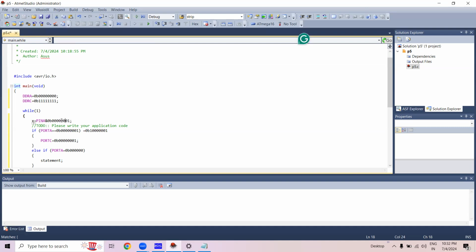We are asking the pins of port A to multiply logically with this code, 00000001. We have an AND gate, and whenever we multiply any pin with 0, it gives you 0 output. That means if any pin of port A except A0 holds the previous logic, you can make it 0 simply by multiplying, or masking. This process is known as the masking process.